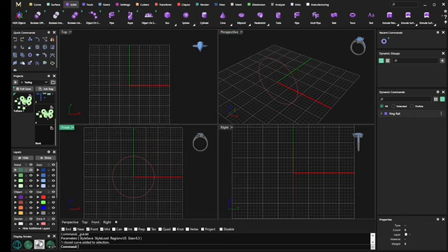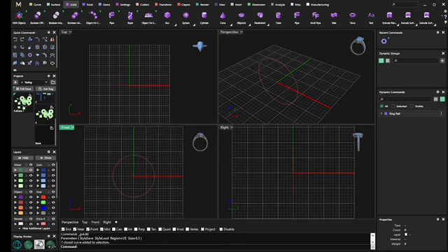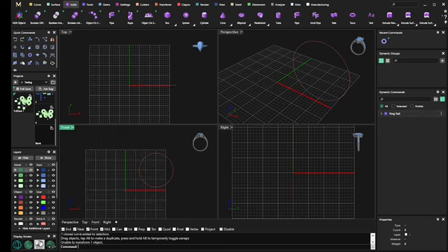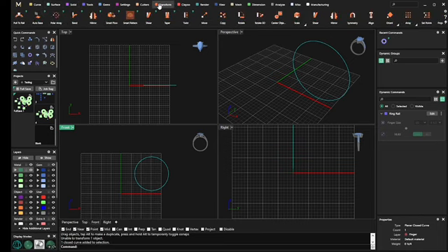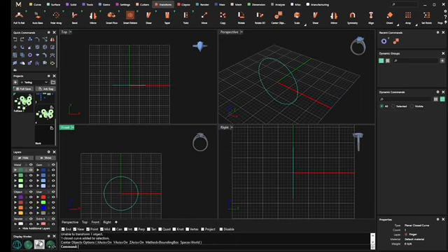Okay, you want to keep the ring rail right where it's at. You don't want it to be moved. It is in the center of F4. And so if, let's just say you accidentally move it and you don't notice it right away. Oh, how are you going to fix that? You can select it and go up to transform, center object, press enter.